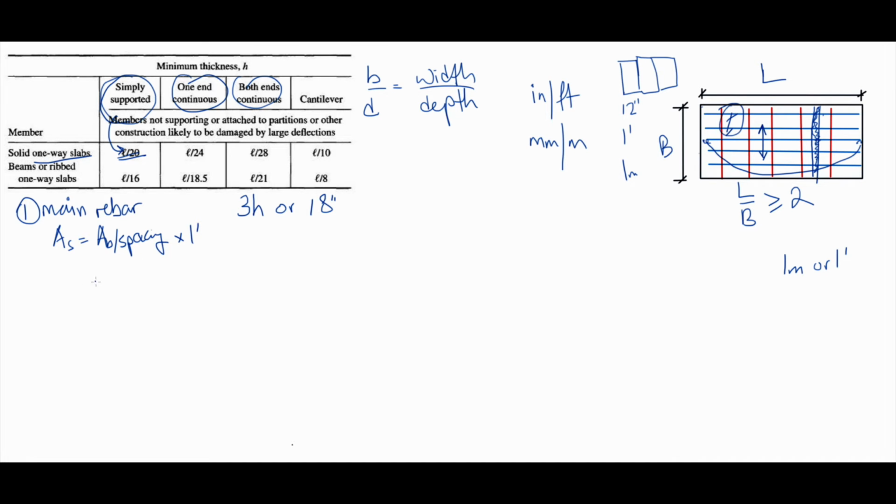Talking about the other type of rebar, which is called temperature and shrinkage reinforcement. This is for understanding why it is there. We use it to hold the main reinforcement tightly. We're going to see it in 3D in the next slide. As concrete hardens, it shrinks, and because of differences in temperature, winter and summer, it shrinks and expands due to the temperature stresses.